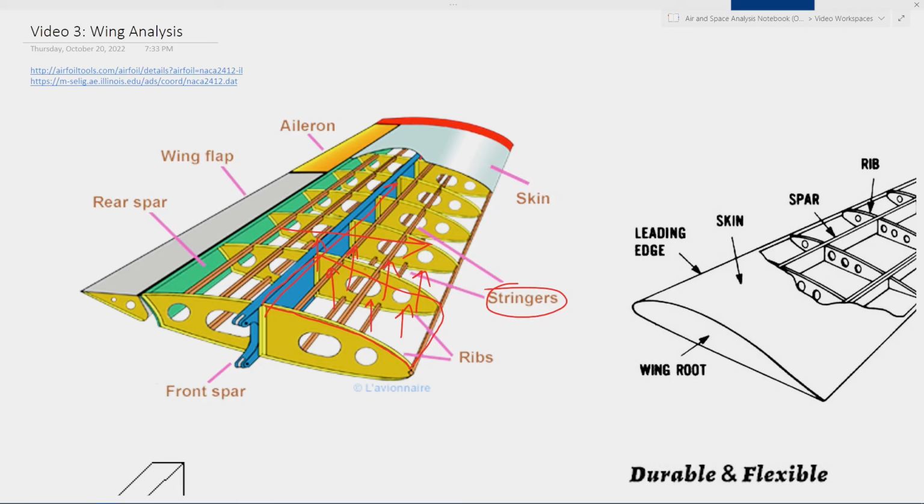And all of this area through here is unsupported, and the pressure is pulling on it, or in the case of the bottom of the wing, it's pushing on it. Maybe that's a bit easier to imagine than pulling: imagine you just put a sandbag on the skin and it's pushing on it. And like we said, the skin is only 1/16 of an inch, so it's not stiff when you're trying to bend it around its thin axis.